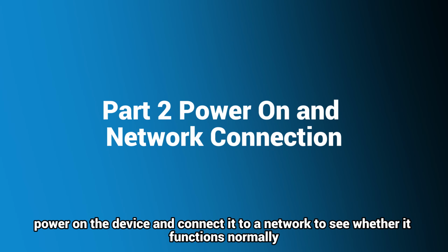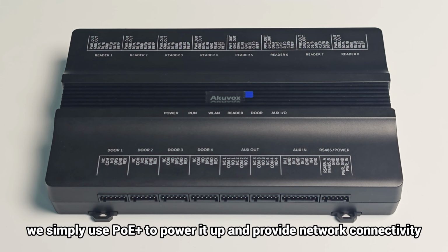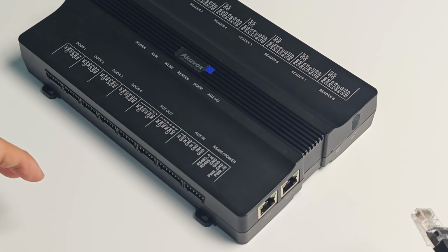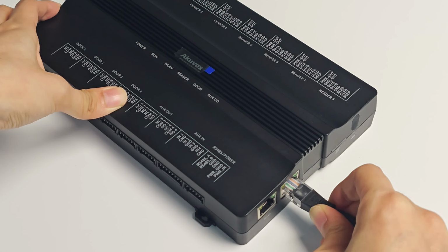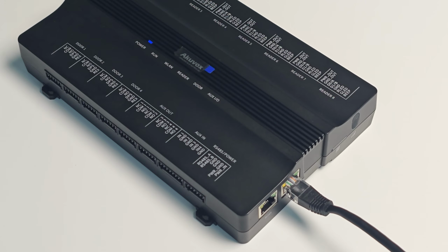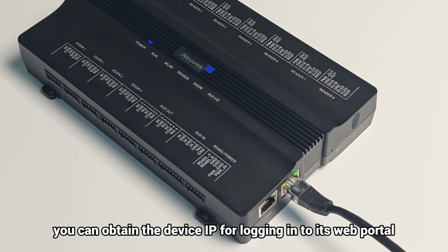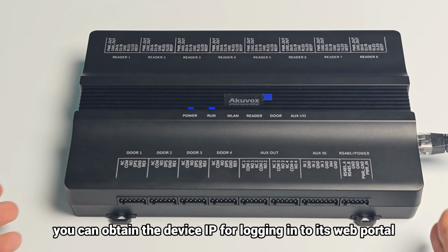Before wiring, power on the device and connect it to a network to see whether it functions normally. In this video, we simply use PoE Plus to power it up and provide network connectivity. The blue power indicator light and flashing run indicator light indicate that the device has finished initialization and all features function normally. Then, you can obtain the device IP for logging into its web portal.